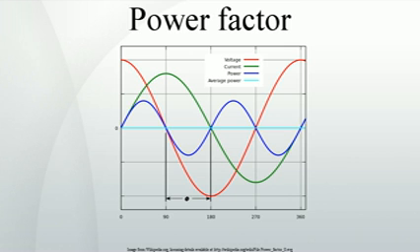The reactive elements can create voltage fluctuations and harmonic noise when switched on or off. They will supply or sink reactive power regardless of whether there is a corresponding load operating nearby, increasing the system's no-load losses. In the worst case, reactive elements can interact with the system and with each other to create resonant conditions, resulting in system instability and severe overvoltage fluctuations. As such, reactive elements cannot simply be applied without engineering analysis.